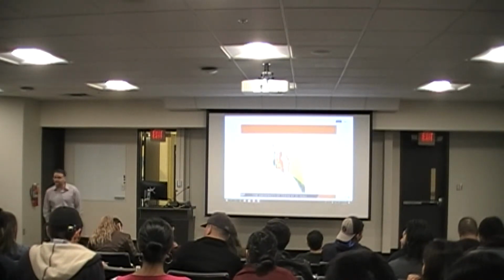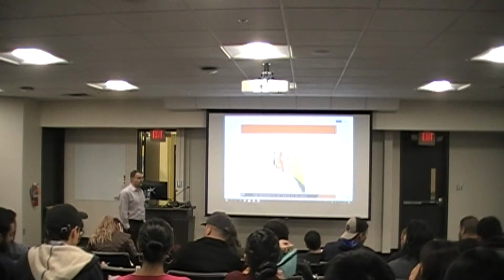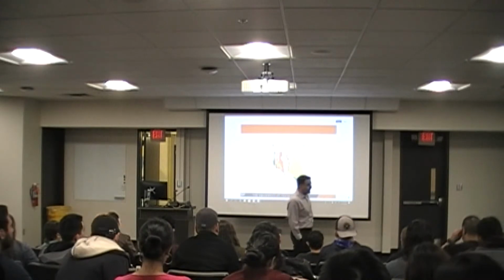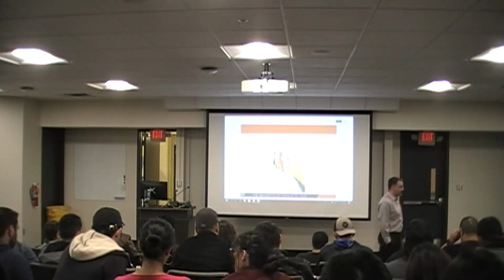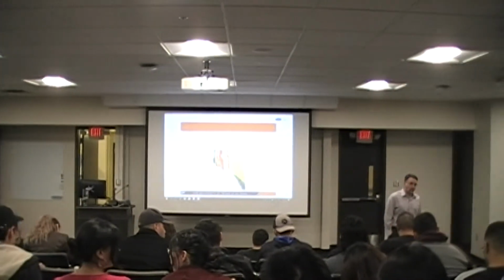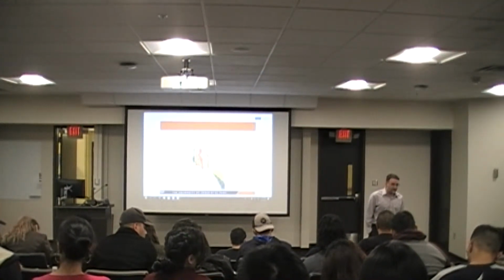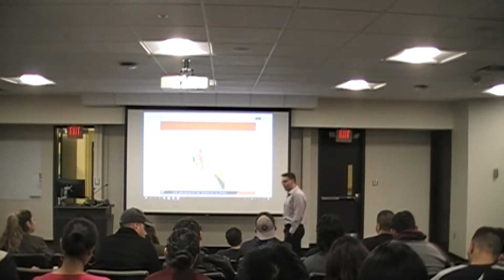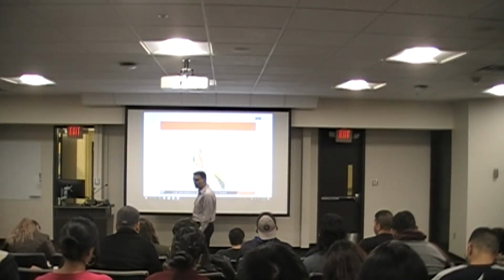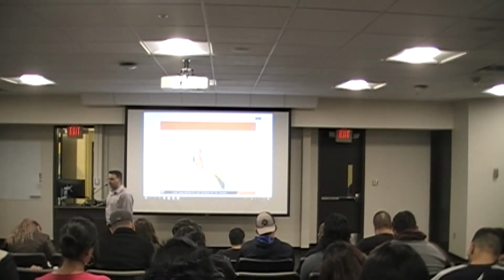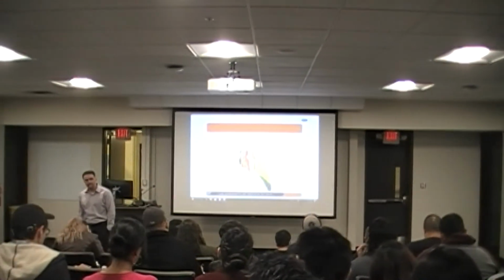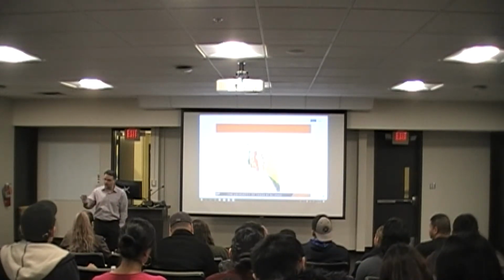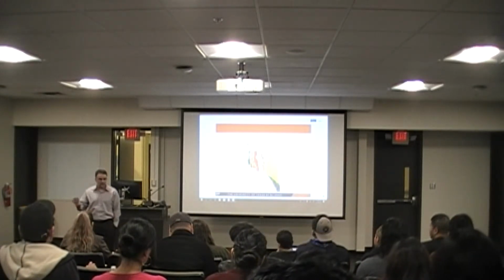What is CL? C, the first one, is particle size. C was for clays, and L was related to low plasticity, right? So you have CL, that would be clay with low plasticity. How about MH? What was M for? M was for silt, and H was for high plasticity. How about SP? S was for sand, P was poorly graded, and that would be an SP.